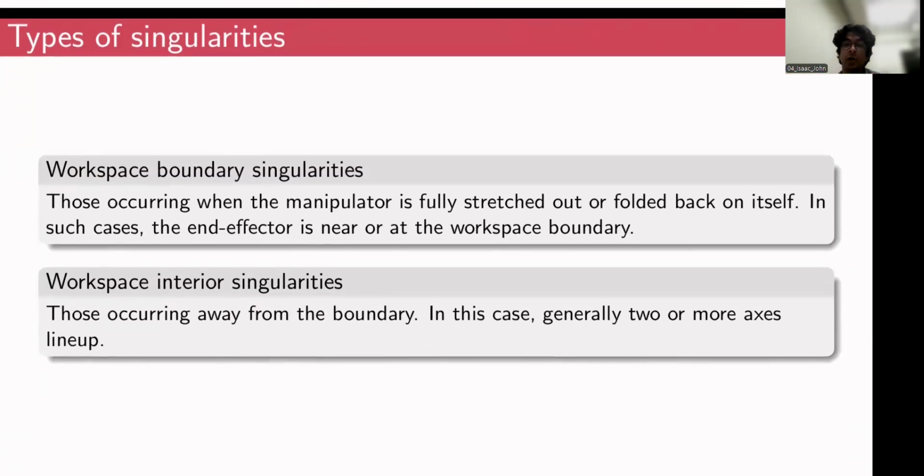These singularities basically occur when your Jacobian matrix becomes singular. That's why we call it a singularity, right? And the Jacobian matrix becomes singular when the constraint equations become dependent. And the reason constraint equations become dependent is because of the joints aligning. When 2 prismatic joints are parallel, it will cause the same motion.